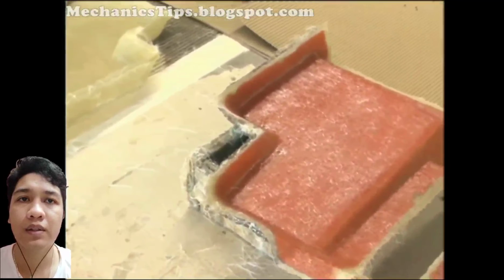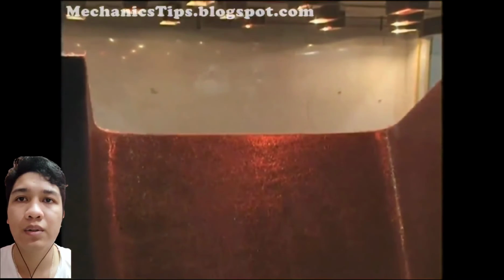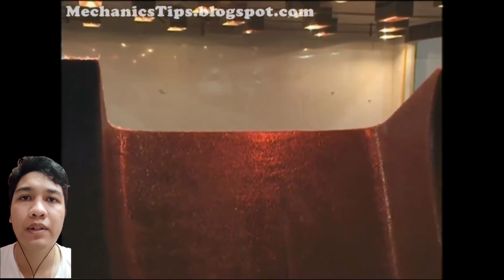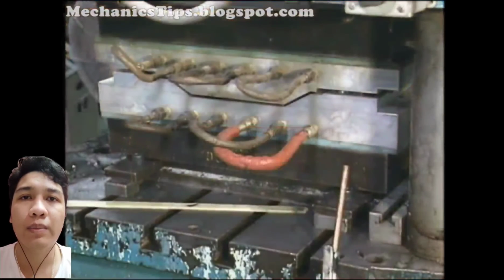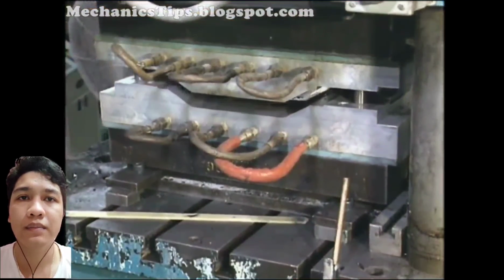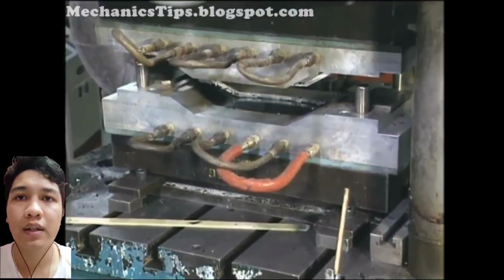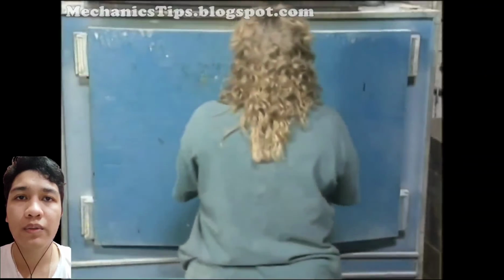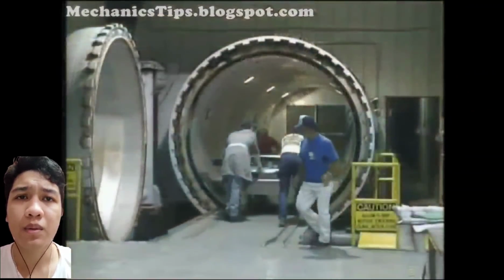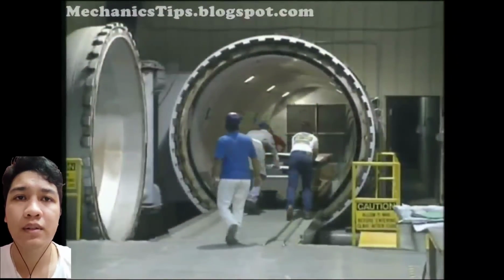After production, composite parts may be allowed to cure at room temperature or with open air heat assistance. Composite parts are also commonly consolidated and cured in heated platen presses, ovens, or autoclaves.